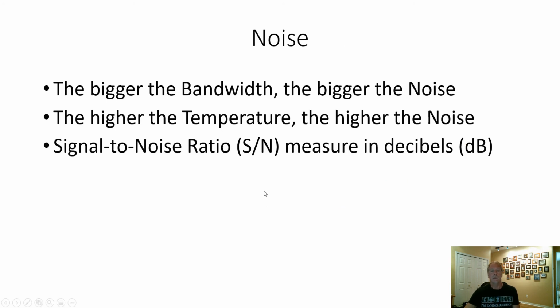Let's talk about noise, my favorite subject. You all know the bigger the bandwidth, the bigger the noise. Wider bandwidth equals more noise. But it's also related to temperature. So noise is related to bandwidth and temperature. The higher the temperature, generally the higher the noise.